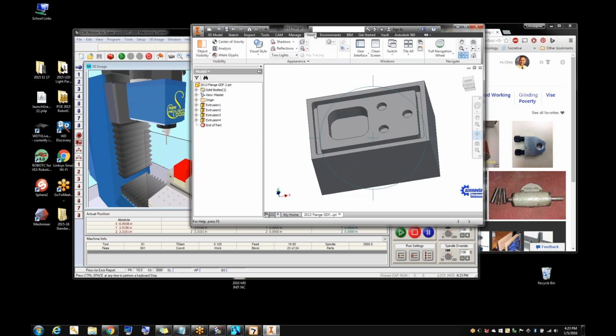And whoever designed this originally, the fillets that are in those corners, they're the same fillets. It's not an offset fillet. So it's not truly a slot. Some of your kids may have a hard time getting HSM to want to call that a slot. Some will do it right away.